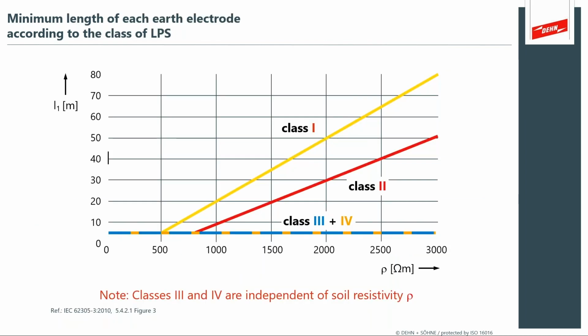And what's really interesting from the IEC methods is the class of lightning protection can help drive your design of the earthing system, so that you can by design intentionally drive the improvements to get a more effective soil earthing electrode attachment. So we talk about in the class 1 system, you'll have a smaller rolling sphere, and that smaller radius for the rolling sphere will drive the placement of the air terminals, but also it will drive the design of the earthing system.